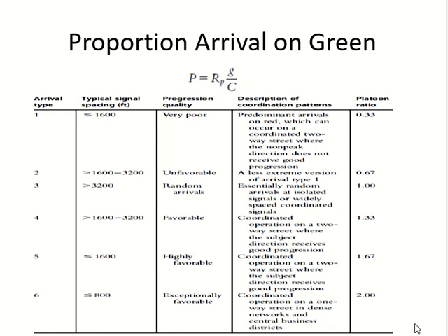Yes. Okay. So just remember, we are going through the steps for the operational analysis of signals, meaning finding out the level of service for the signals. We have discussed input data, and it requires you to find out lane groups and movement groups as well. Then we discussed saturation flow rate, the base value and the adjusted value.